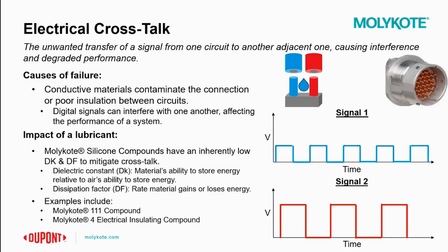These products have an inherently low dielectric constant and dissipation factor, which means they greatly resist the transfer and storage of electrical energy. When introducing a MOLYKOTE compound to a multi-pin connector, the product acts as an electrical insulator and prevents crosstalk between these adjacent pins. It effectively isolates and protects the electrical signal through each individual pin.